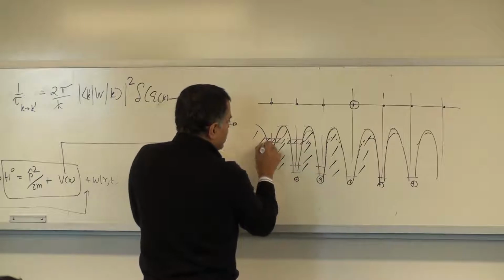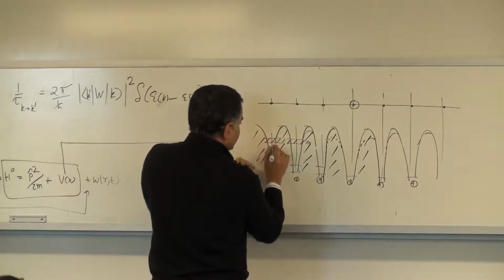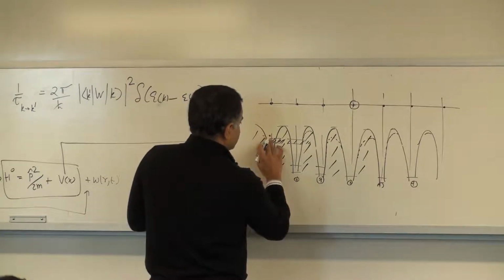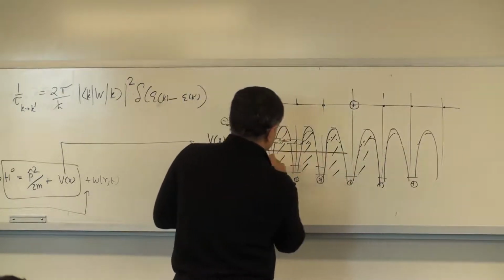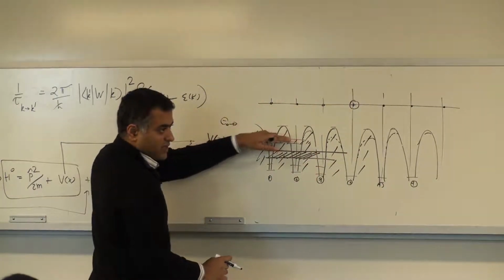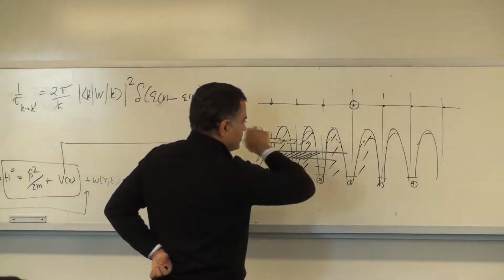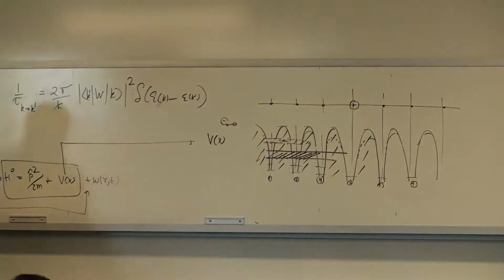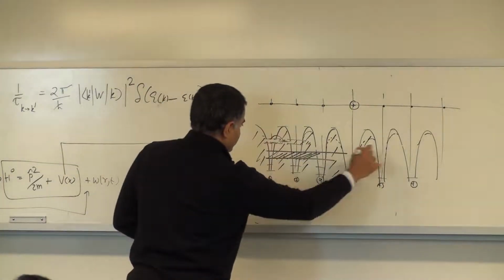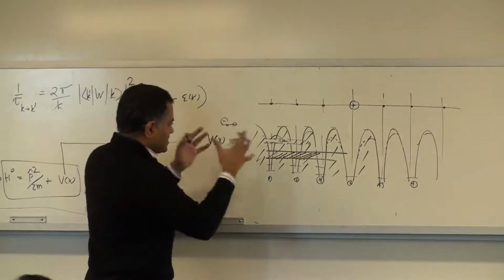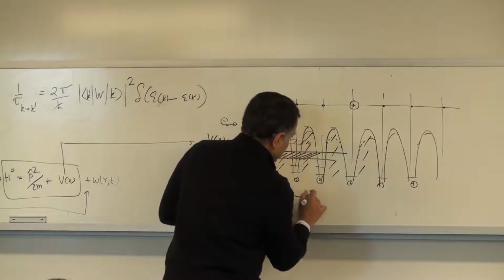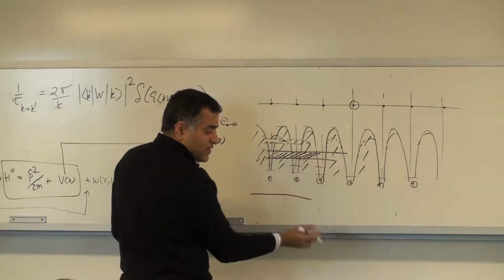And when we sketch this, then you reach up. So here's maybe an empty band, and then this one maybe is a filled band. This is the valence band, and that's the conduction band, for example, right? Conduction band electrons can move, being wave-like particles. There's a certain probability that they can actually move across, and all that is captured in the fact that we are using this effective mass picture with a very sharply defined conduction band and sharply defined valence band.